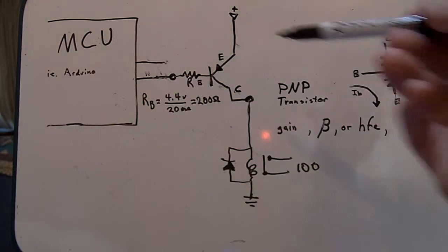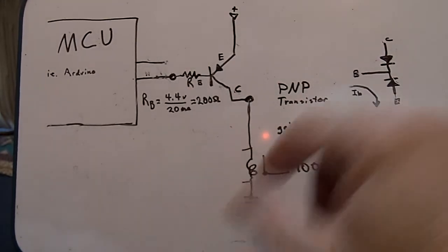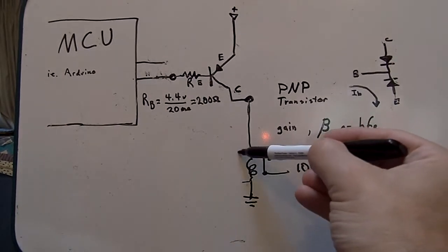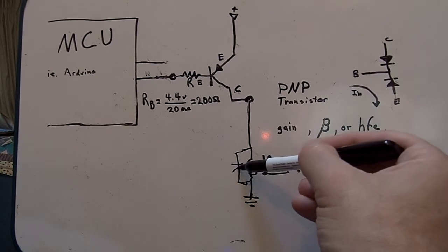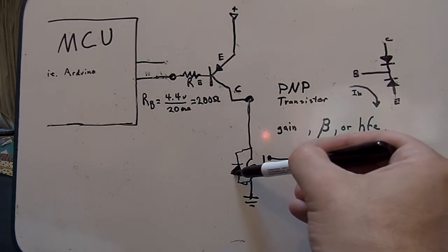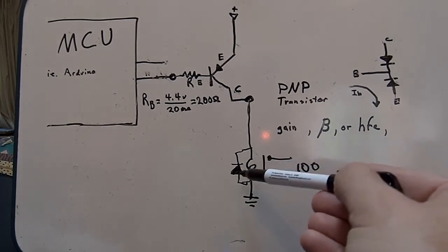So there's 2 approaches here. You can use a transistor with plenty of voltage ratings and not even bother with this. Just what I tend to do. The normal good practice is to put a diode here. The thing about putting a diode here is you actually have to derate your terminal slightly. And I know some of you won't believe me, but look it up. So you actually don't get quite as hard of a slam on the contacts as you would if this diode wasn't here.